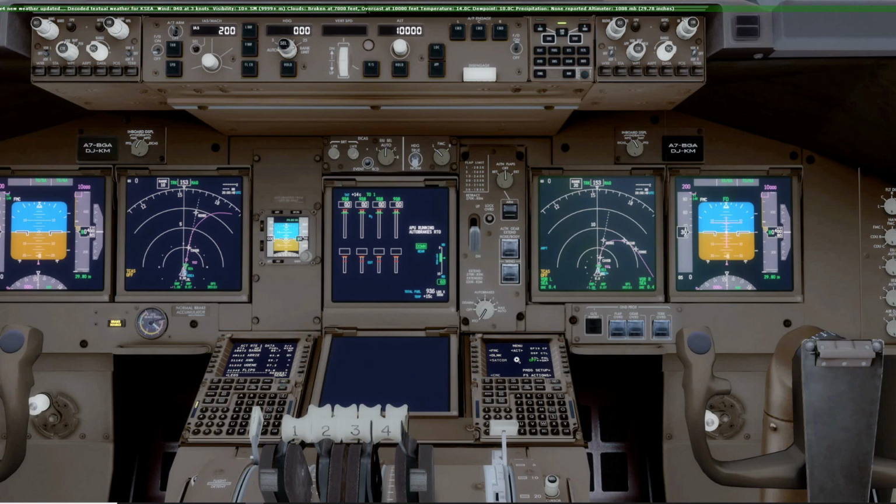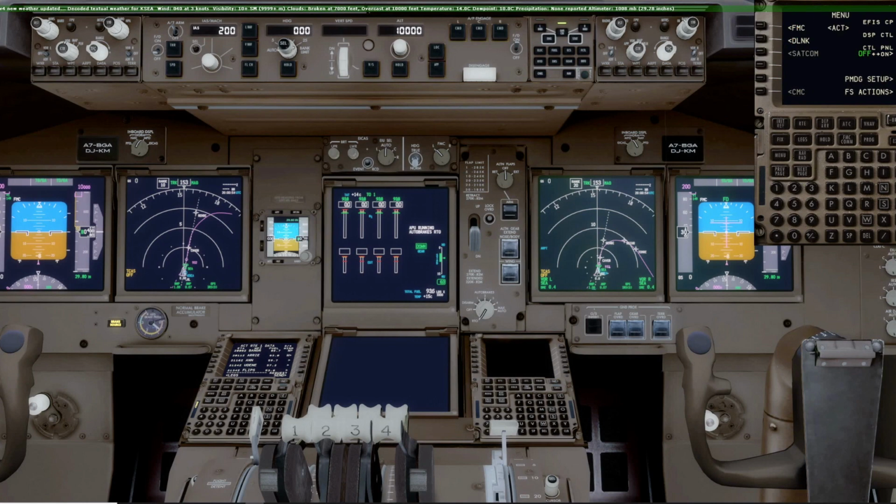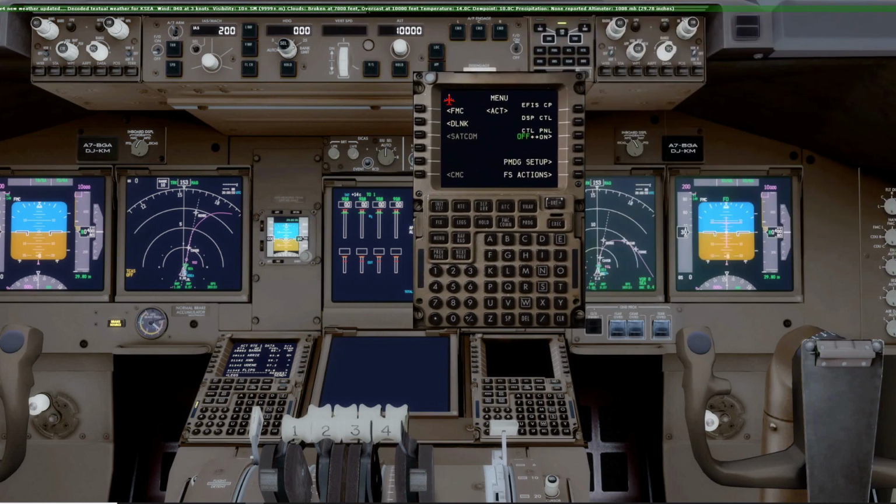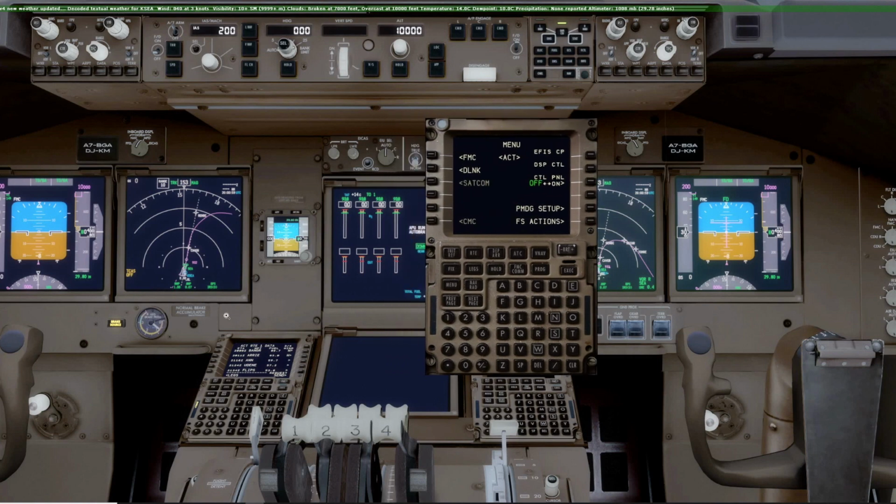And then from here we come down to the CDU, and if I'm the first officer, then I'm going to check if the captain was the person to do the CDU pre-flight. Let's say he's the pilot flying, so maybe he did the CDU pre-flight, then I'm going to check it. If I'm the one that did it, then the captain's going to check it. So again, I'll go to FMC and check my model, engines, and I'll go through the whole sequence again. Position initialization page, check there. Route page, check the route. I'll go over it with a flight plan.